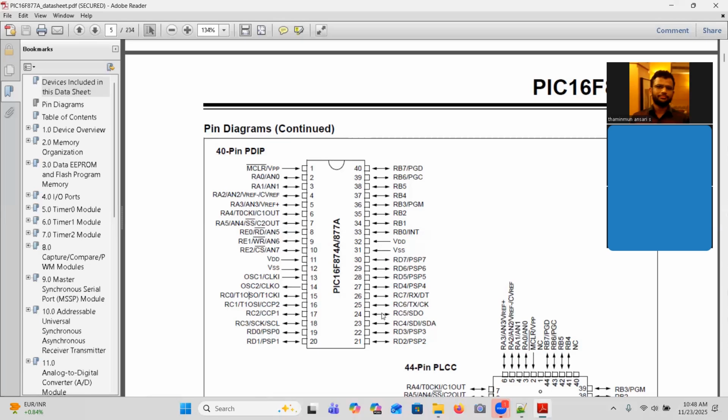It is actually a piezoelectric material. When you just supply power, it will generate voltage pulses. Those pulses act as the operating clock for this microcontroller. This is the oscillator. If you look at any motherboard, there will be a cylindrical or a hex, some sort of rectangular clock.